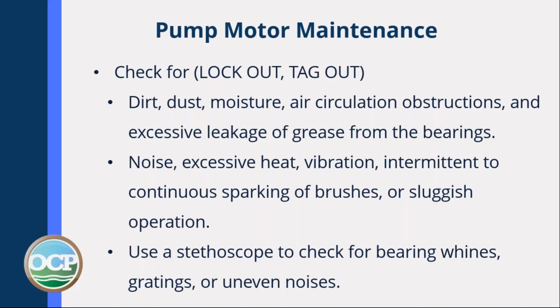Pump motor maintenance. Before you work on any pump motor, make sure you check for lockout, tagout. Make sure all forms of energy are locked out and disconnected. That's not just electricity, but hydraulic, air, anything that can cause somebody to get hurt.